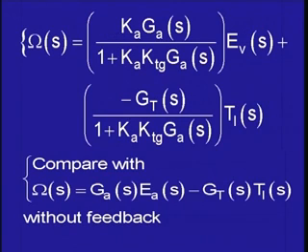And therefore, we can find out the appropriate value of the reference voltage, so that under rated conditions the speed will be at the nominal value, and we can compute this by using the final value theorem.